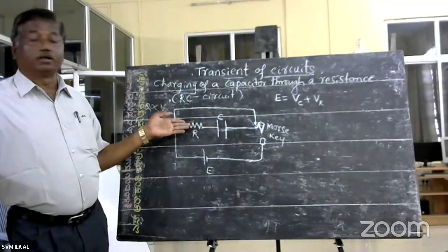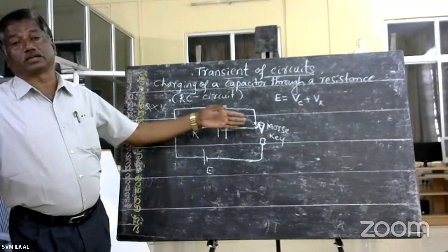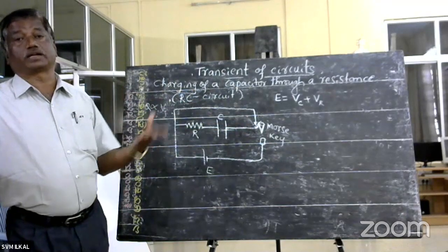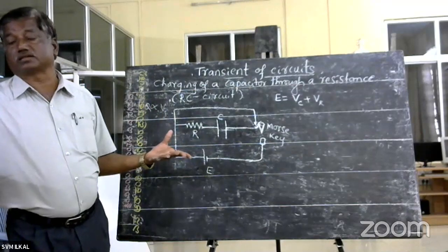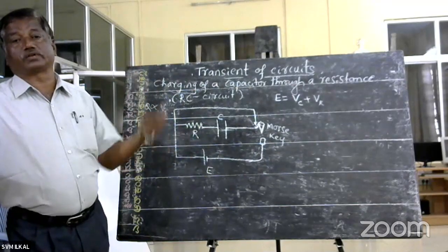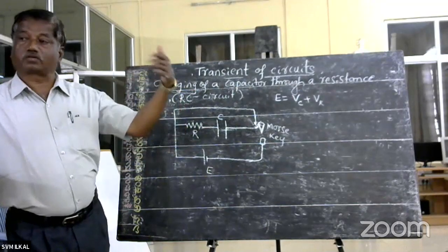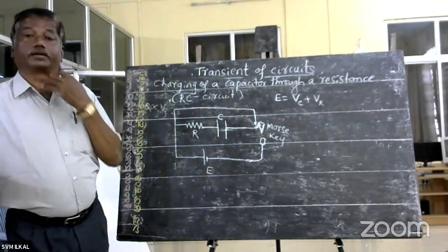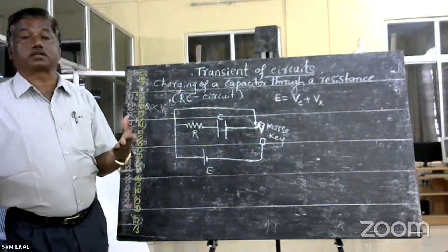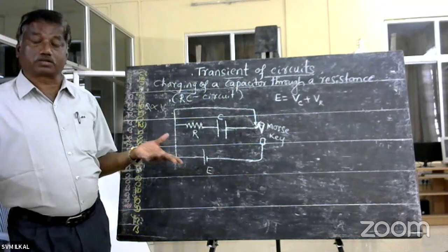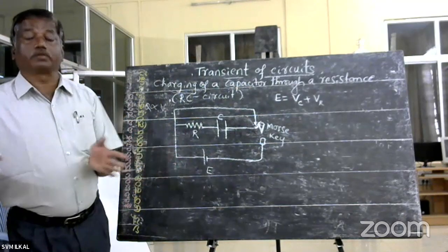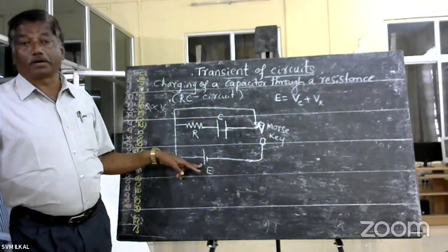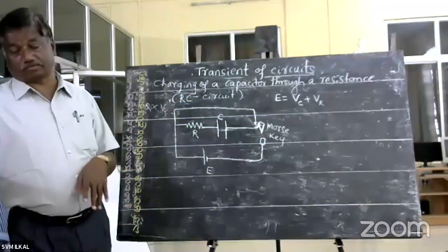If R1, R2, R3 are three resistors connected in series, and a certain voltage, about 10 volt, is given across the three resistors, the voltage across R1 is different, across R2 is different, across R3 is different, because R1, R2, R3 are different. If all three resistors are the same, the same voltage is developed across each, but the sum of the voltages across the three resistors is equal to the total voltage applied across the combination.